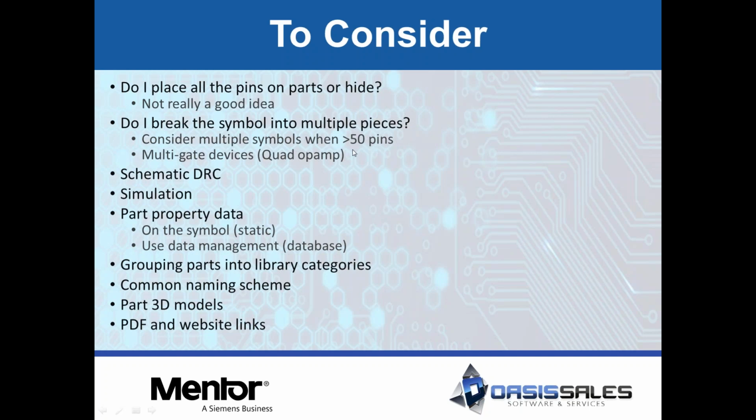So, and then, do I make gated devices? Do I separate the symbols out into individual pieces? We've been doing this for years, obviously, with op amps and inverters and anything that has the same function in the same chip multiple times. You break them up into multi-gate devices. But some of the newer engineers out there may not know that's a thing. So consider that when you're making your parts. The biggest thing in breaking up symbols is making your schematics readable. Spreading out the same part over multiple pages, and letting the tool manage everything is a good thing to consider.